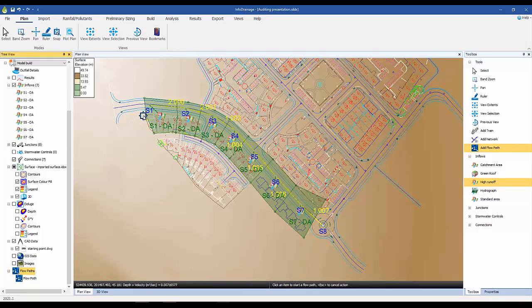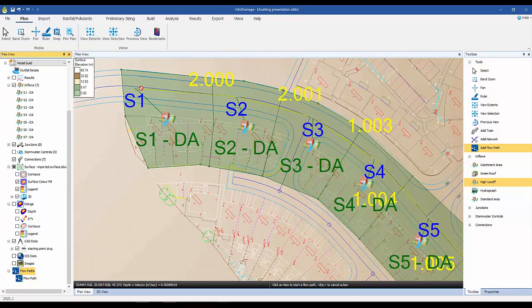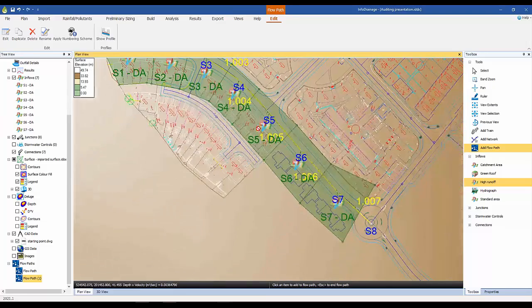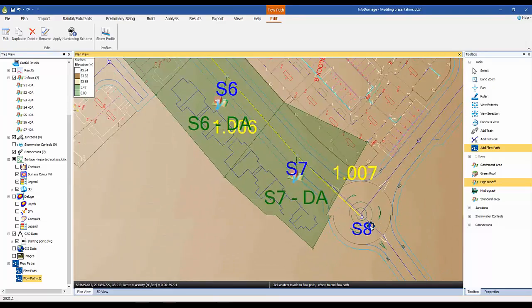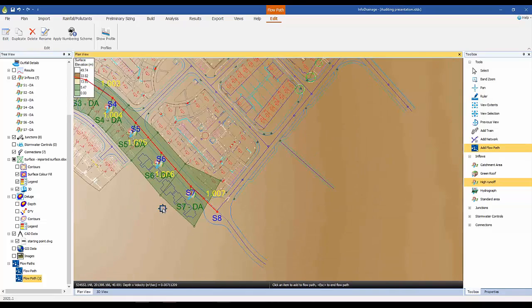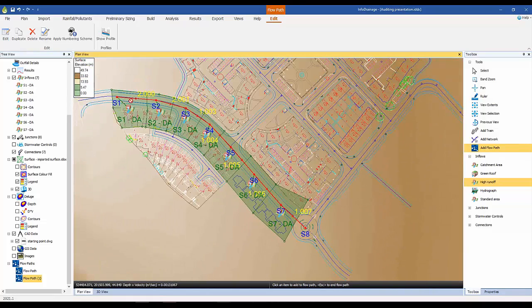We can see we've got this square value. I'm going to click on a manhole there, zoom out and zoom down to where I think the outfall should be. And what I'm looking for firstly is just, do I have this green square? If I do, then it shows that these two locations are connected. So click on that and I've created my flow path. So this is an important check to say, is everything connected from here down to here?